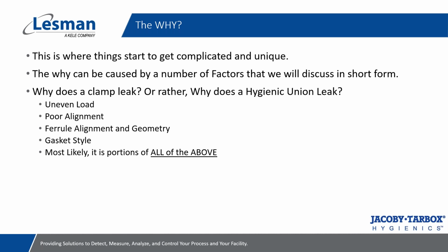I have witnessed on brand new equipment that was trying to be installed that ferrule A was not identical to ferrule B just because they came from two separate sources. We had an application where on a vessel a ferrule was actually warped slightly out of shape during the welding process and was not allowing it to mate with the sanitary gasket in the opposing ferrule in order to geometrically be able to be clamped together.